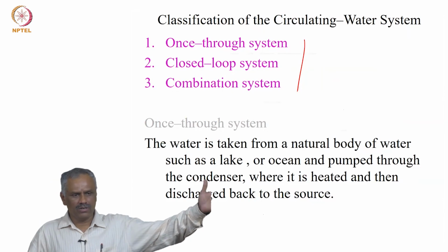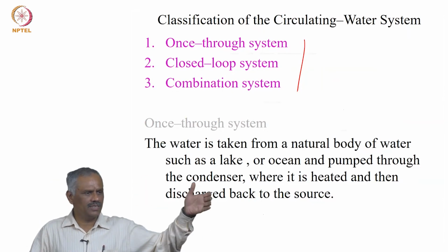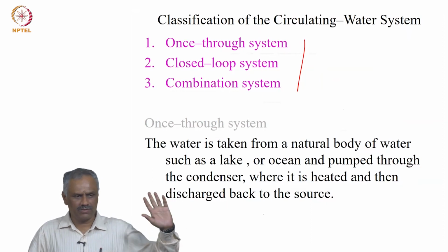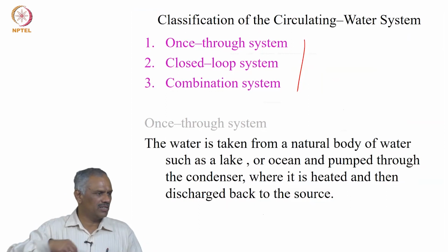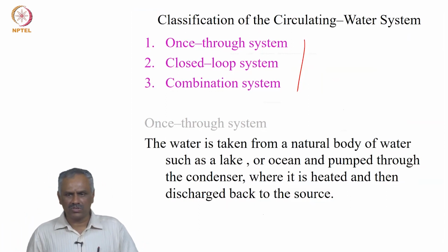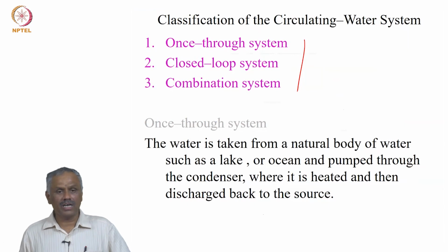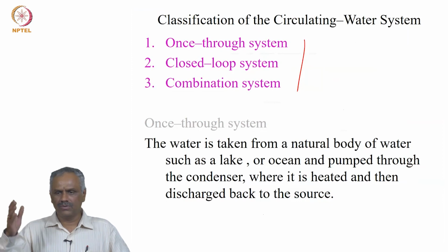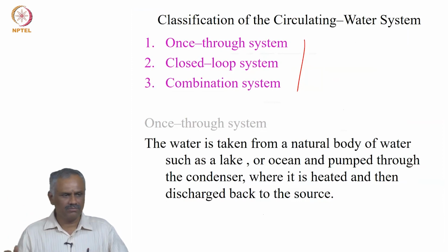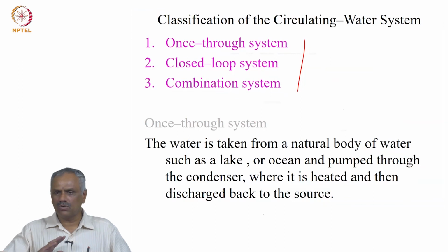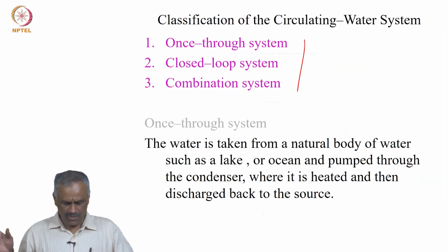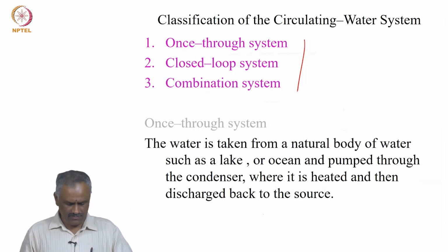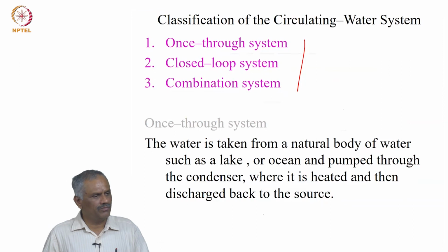See, again in IIT also, for all air conditioning systems, we have a water problem. That is why most of these cooling towers are dry cooling towers. There is no wet, no adding of water into that, only reject into the atmosphere, where you do not have water. Water is, see, 2/3 of heat rejection, you need enormous amount of water, and if you go to the dry areas where you do not have water at all, then in such case you have to reject into the atmosphere, air. Okay. So, you need different types of circulating systems here, mainly when you want to reject heat.